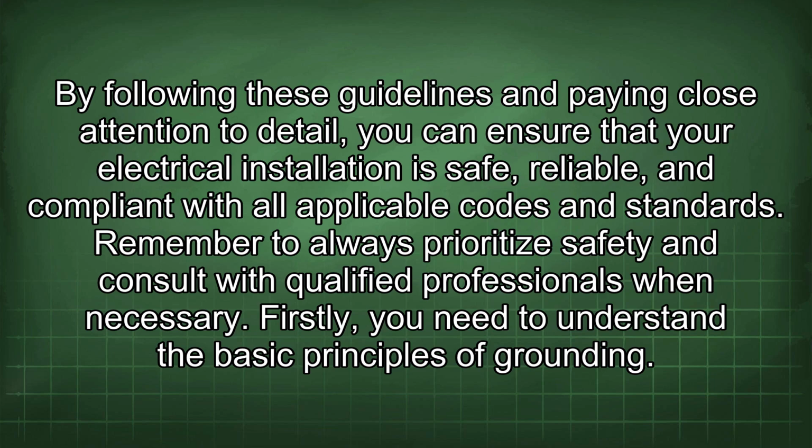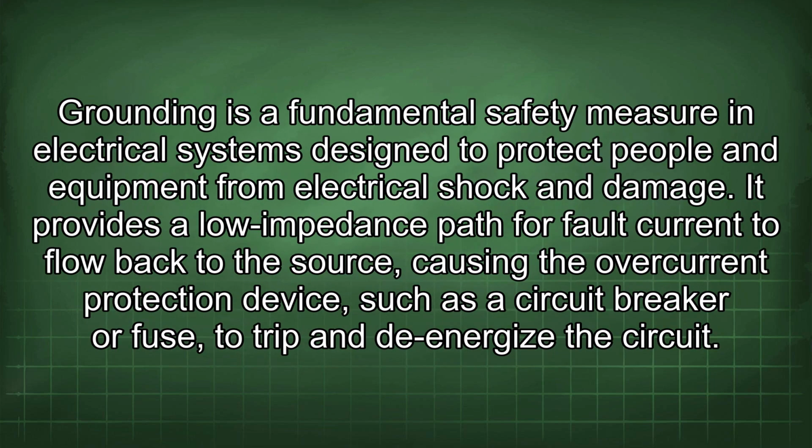Firstly, you need to understand the basic principles of grounding. Grounding is a fundamental safety measure in electrical systems designed to protect people and equipment from electrical shock and damage. It provides a low impedance path for fault current to flow back to the source, causing the overcurrent protection device, such as a circuit breaker or fuse, to trip and de-energize the circuit.